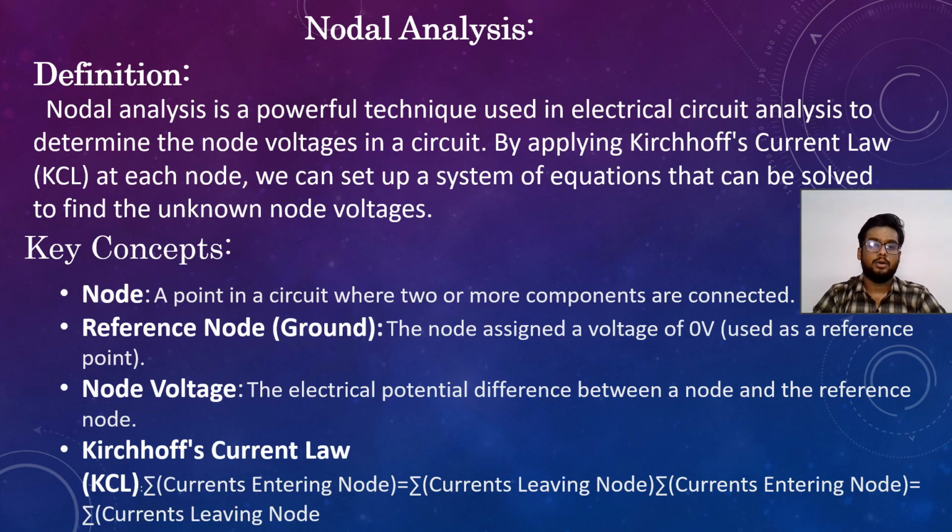First of all, let's talk about nodal analysis. Definition: nodal analysis is a powerful technique used in electrical circuit analysis to determine the node voltages in a circuit. By applying Kirchhoff's current law at each node, we can set up a system of equations that can be solved to find the unknown voltages. Key concepts.